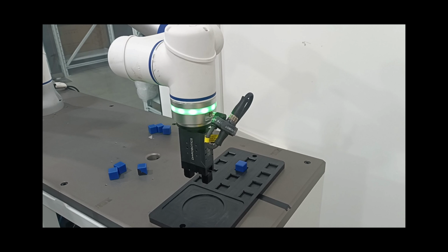Section 3, Safety Tool. By default, the safety plane only detects the flange and joint 3 if Restrict Elbow is checked. To make the end effector detectable by the safety plane, the safety tool needs to be configured as well. To make it simple, configuring the safety tool involves making a virtual sphere that can cover the end effector. When the safety plane detects this virtual sphere, it will trigger the configured safety action.